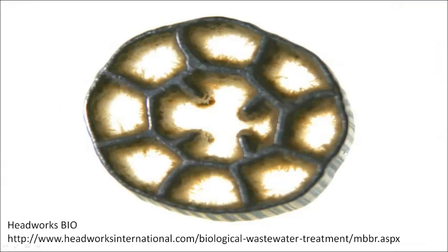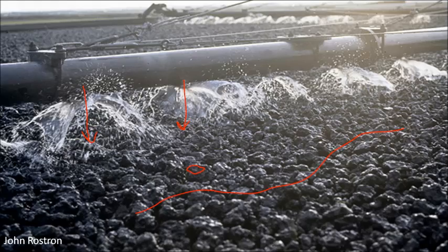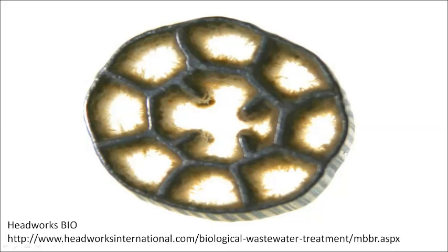So the dissolved organic matter gets decomposed into inorganic matter. Okay, this process is called mineralization. And then that inorganic matter is absorbed and utilized by the biofilm microbes. So here we see a picture of, I think it's actually the same thing that was in this original picture here, some sort of synthetic object or polymer, and you can see the biofilm growing on the inside of whatever this matrix is made of. And it's designed on purpose to have a large surface area so that all of the different organic material in the wastewater, as it passes through, can feed this biofilm.